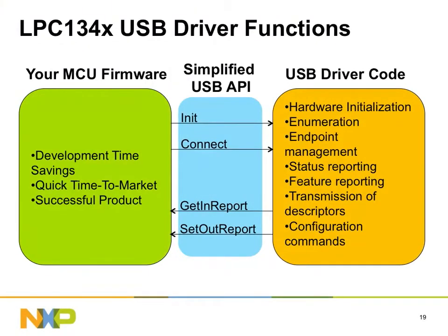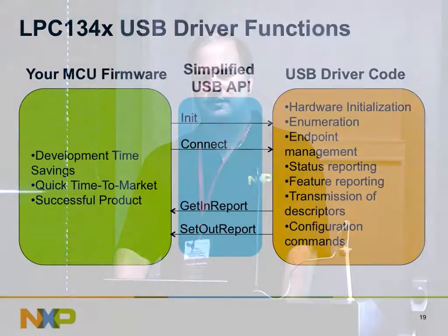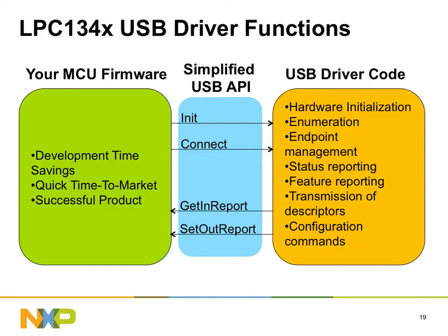So this is the interface to those drivers that are in ROM. It's very, very simple. All your program has to do is call a couple of functions, one to initialize and one to connect to the USB block. And again, these are entry points in the ROM that you call. And you supply your own get and set report functions, which the ROM code turns around and calls back again to do its functions.